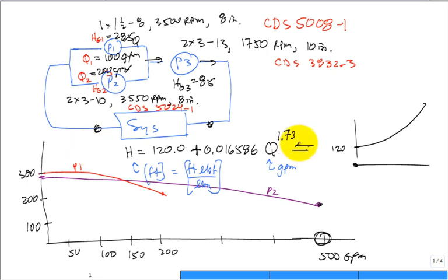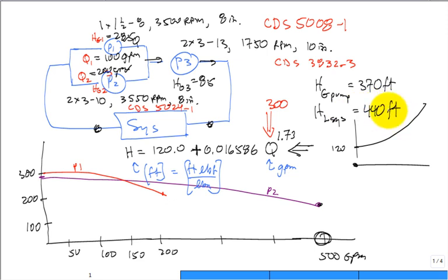Let's just see if we, by eyeball, balance the system. What is our actual head loss when Q is 300 GPM? Somebody will have a calculator. You want to run that? So our head gains from all the pumps was around 370 foot. Now what is our head loss through the system if it's actually 300 is the balance? If it's 440? How many people agree? Thumbs up if you agree. That's what you got? All right.